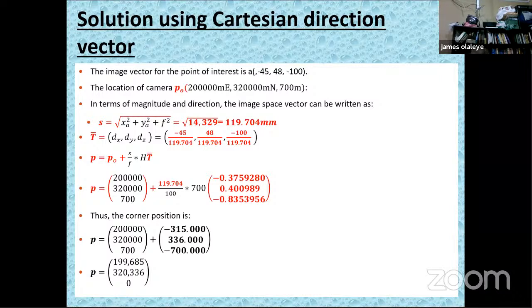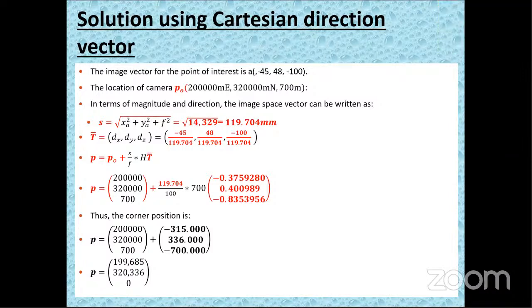The manufacturers will tell you this thing has a 3 cm ground resolution, or it has a 0.5 mm image resolution. So once it is like that, if you want to use this for something that is either worse or better, you have to vary the distance at which you capture your image. Okay? Is that clear? Yes, sir, it's clear, sir. Thank you, sir. Any other question along the line?